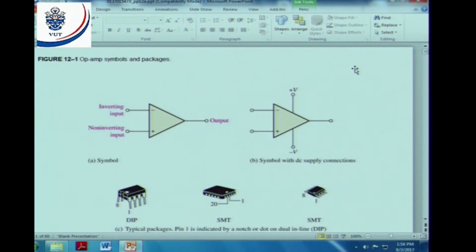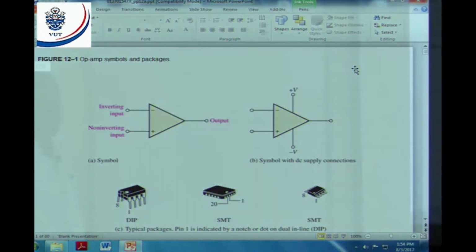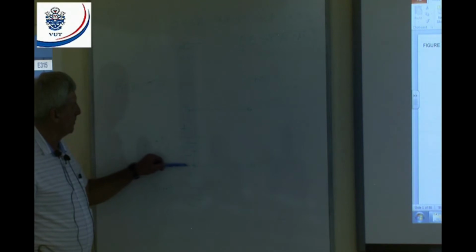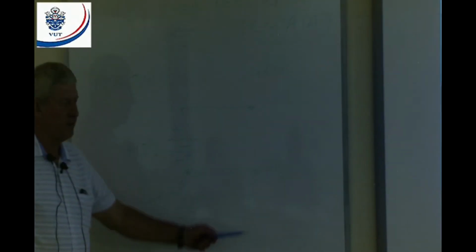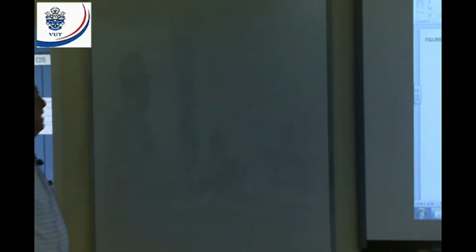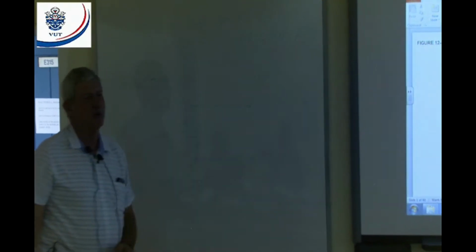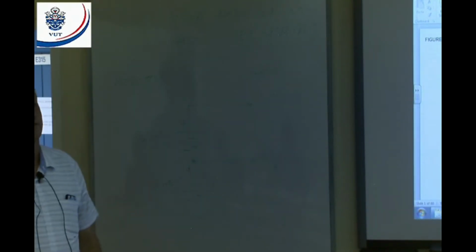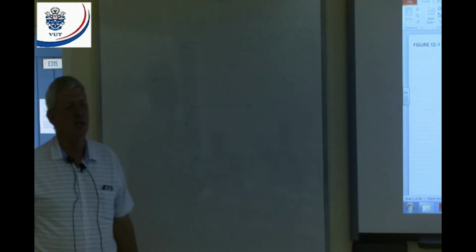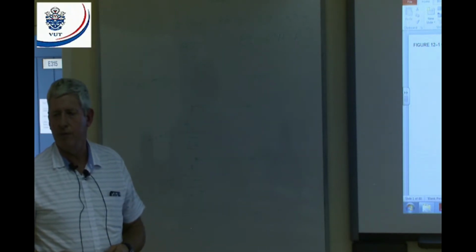Now here I made a drawing, it's not very clear. But if I take two 15-volt batteries, connect them in series, take the one output there, take the center point to that, that'll be my 0 volts, and that'll be my negative. That means if I put a black lead of a multimeter here, the red lead there on a voltage scale, it will give me plus 15 volts. Black lead there, red lead there will give me minus 15 volts, all right? If I put my black lead here, my red lead there, what will it give me? It will give you 30 volts because they're in series, negative, positive, those voltages will add up. It won't give you 0 volts, it will give you 30 volts.